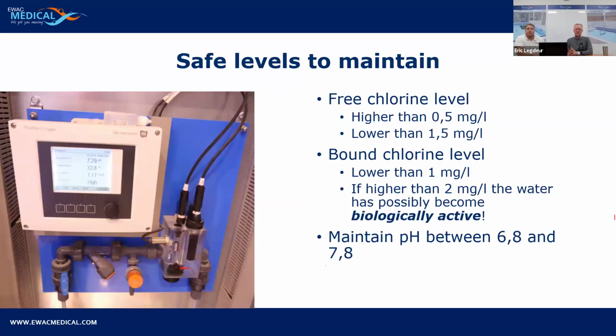Now, these are the important facts that you as a therapist should know. Maintain a free chlorine level higher than 0.5 and lower than 1.5. Keep the bound chlorine, so the chloramines, lower than 1 milligram per liter. And if the bound chlorine is higher than 2 milligrams per liter, then possibly the water has become biologically active.